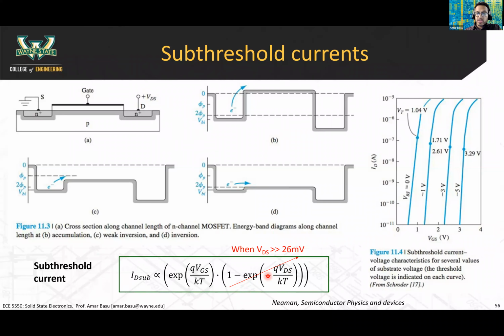But when VDS is greater than 26 millivolts, this entire second term becomes very small, so it just becomes 1, and you're just left with this portion here. At any appreciable VDS, greater than 26 millivolts, you'll just be left with this exponential of Q VGS over KT.